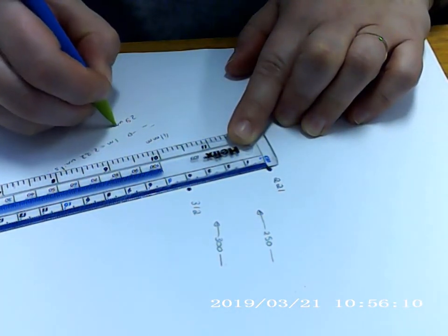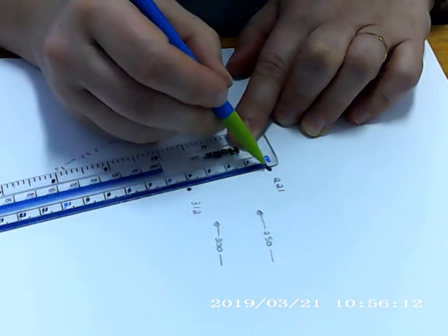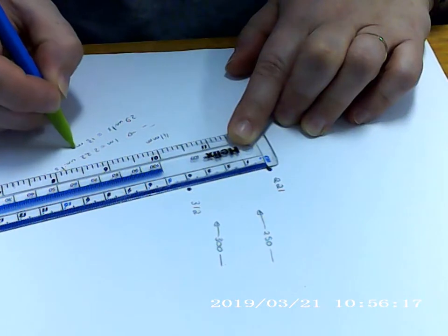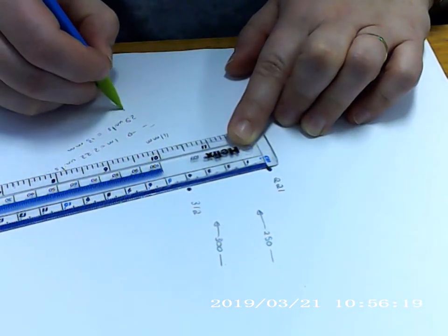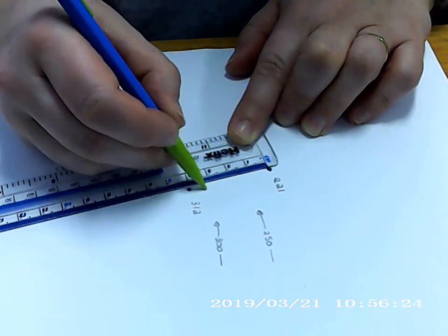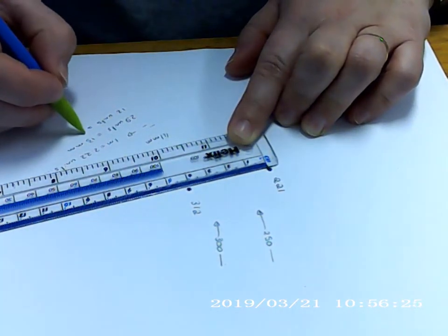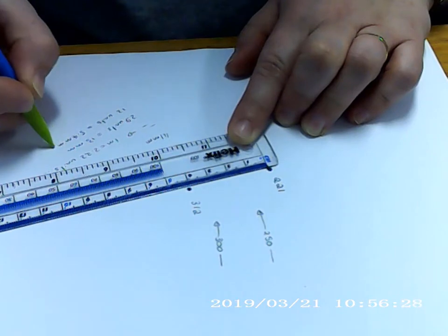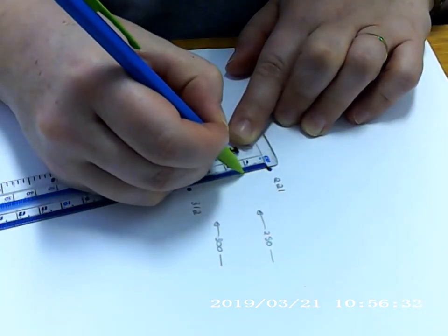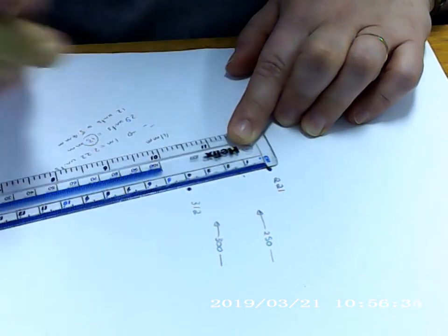That means that if we were to place a contour every unit, there would be evenly spaced contours between the points. We can start by measuring the distance between the 2 points, and we know the difference in unit value. Taking these 2 numbers, we can work out what horizontal distance 1 unit would be, and therefore work out at what horizontal distance the 250 unit contour should be, and what horizontal distance the 300 unit contour should be, and mark these in. Then we can extend our contours from their current position between our 2 data points.